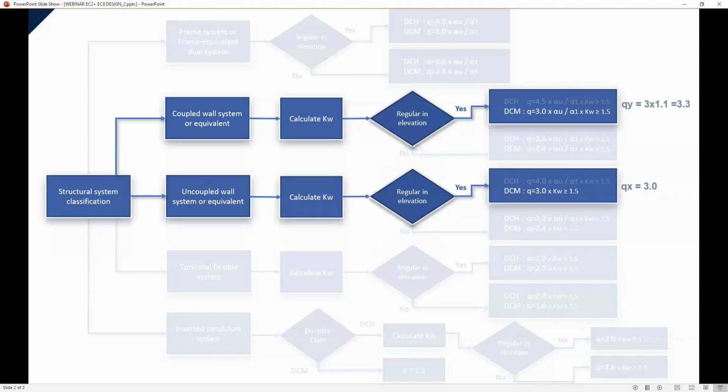Therefore, guaranteeing this proportion only at the base does not seem entirely adequate to us. It works for an initial estimate, and if the value is very low, like 3% or 5%, there would be no problem. But a value close to 15% would not make me comfortable. What other possibilities do we have? We could, for example, check the shears at every floor and the relative shears between the primary and secondary structures. This would require us to create section cuts at every story. Another possibility, which we prefer because it is simpler, is to simply consider the difference in drifts, the relative displacements between floors, for the same load case, comparing a structure that functions only with the primary system against a structure that functions with both primary and secondary systems.